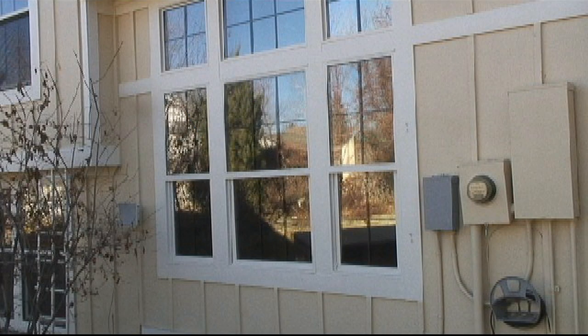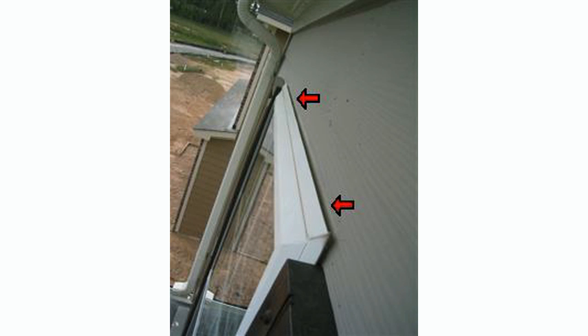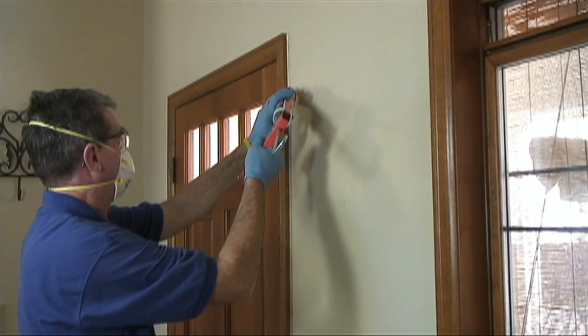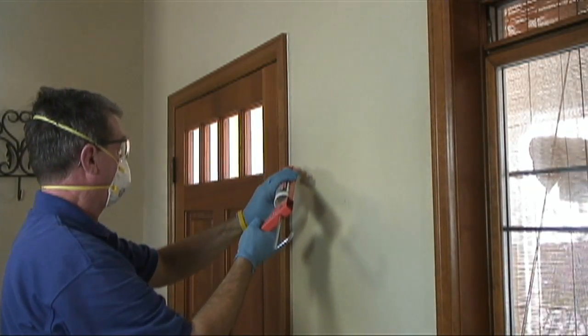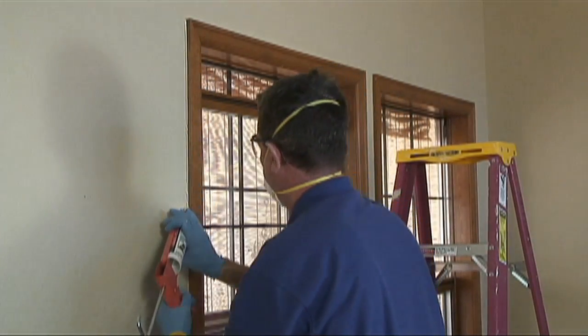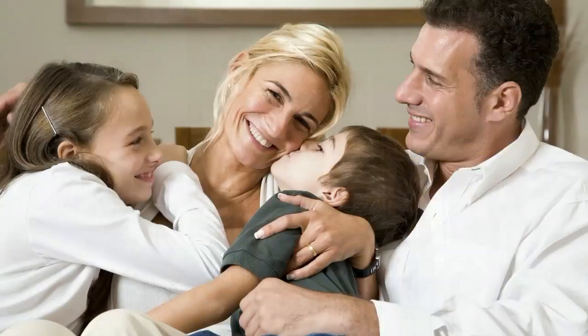You may want to also inspect around the windows and doors on the exterior of your home for significant gaps and cracks that need to be caulked on the outside of your home. This should probably be handled as a separate project. Caulking around your windows, doors, and the gaps and cracks in your home is one of the most economical ways to save energy. You should also be able to feel a difference in the comfort of your home for many years to come.